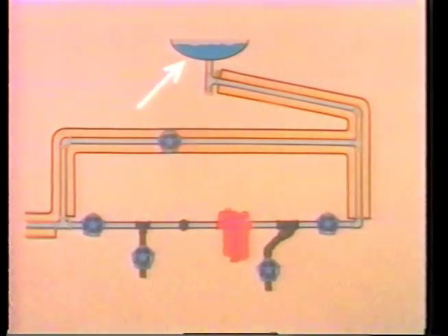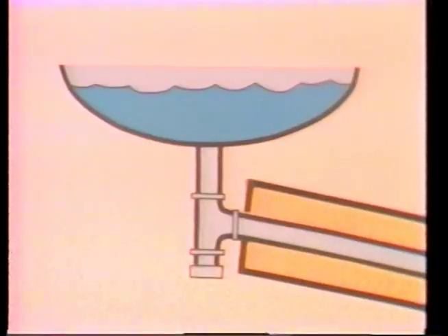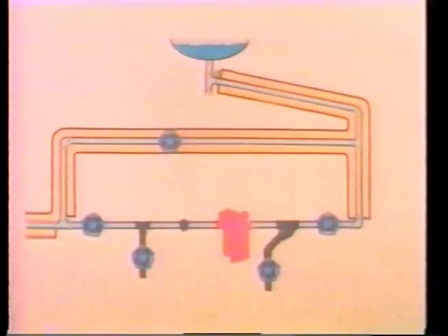Now, first is the steam line or process equipment. Coming off the lowest point of the steam line or equipment is a drip line where condensate collects. The drip line should contain a dirt pocket. This dirt pocket will collect and hold some of the larger particles of dirt or scale that may be in the line. Next is a trap inlet valve that isolates the inlet side of the trap from the steam line